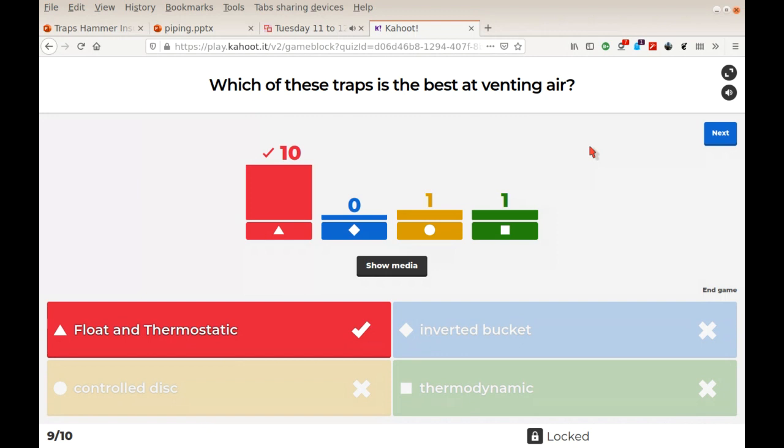When and where do we get rid of it? Primarily on startup, but at times we do volatilize some carbon dioxide and some other things that we can categorize as air. We'll volatilize perhaps a little bit of carbon dioxide in the boiler, especially if we've got carbonate alkalinity. Any kind of carbonate or bicarbonate that enters into the boiler will volatilize and form CO2. And so again, we want to discharge any kind of CO2.